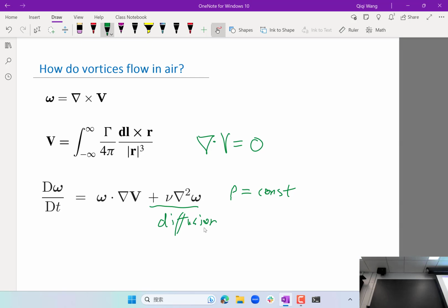And that's going to drive this diffusion term that forms the boundary layer. But otherwise there is no way you can generate vorticity in an incompressible flow field with conservative body force. If you have non-conservative body force, somehow you can generate vortices by using a rotational body force. Yes, good question. Vorticity cannot really be generated away from the boundaries.